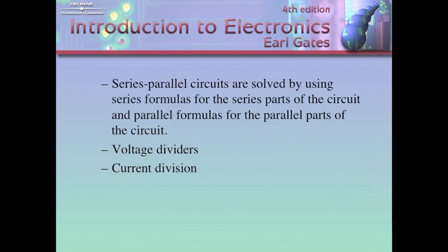This still doesn't help us design this voltage divider circuit. In order for us to efficiently design this voltage divider circuit, we also have to know what the current requirements of these loads are. This might be a power amplifier in your car. If this is a power amplifier in your car, this thing might be drawing 20 amps.